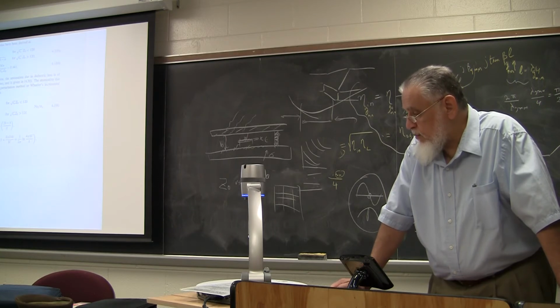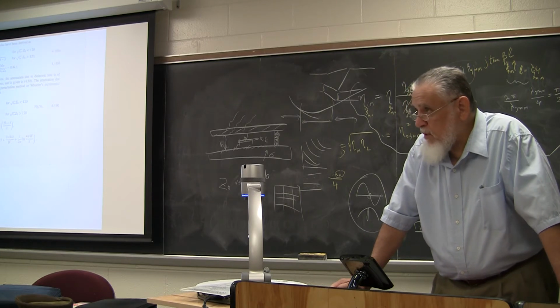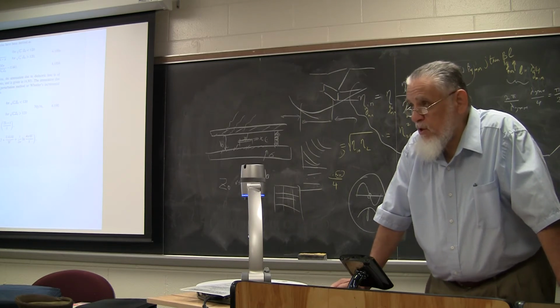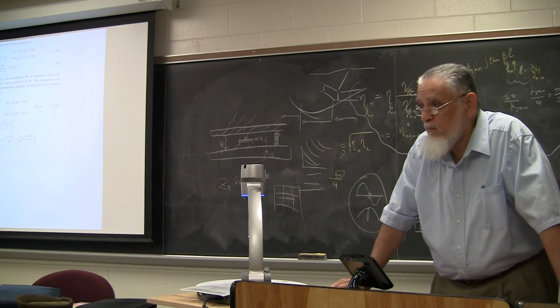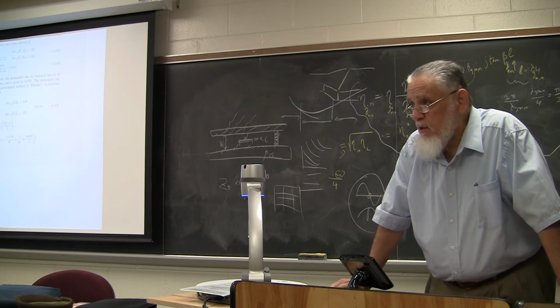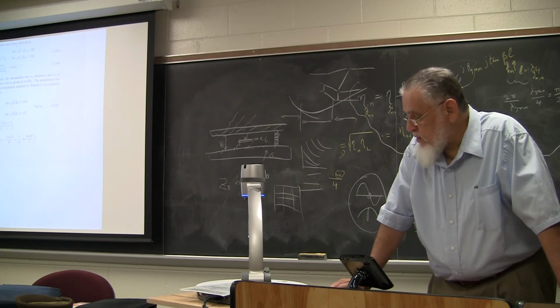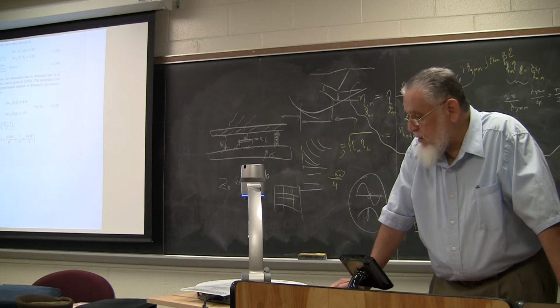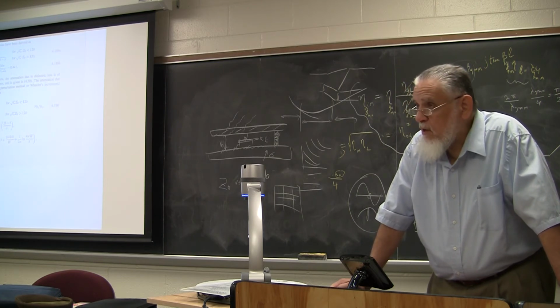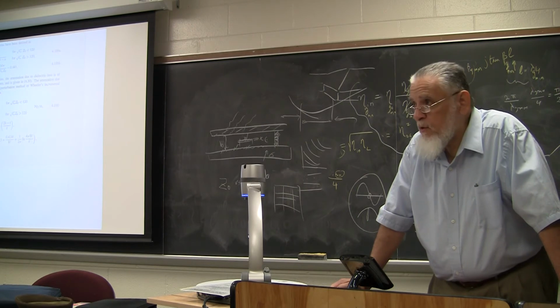So using packages like High Frequency Structure Simulator, HFSS, which uses finite elements. There are many other packages that use finite difference in time domain, finite difference in the frequency domain, and method of moments, and they usually go for the S parameters.